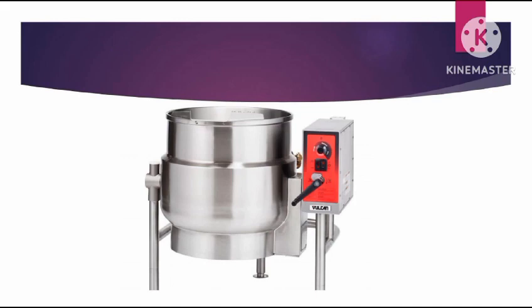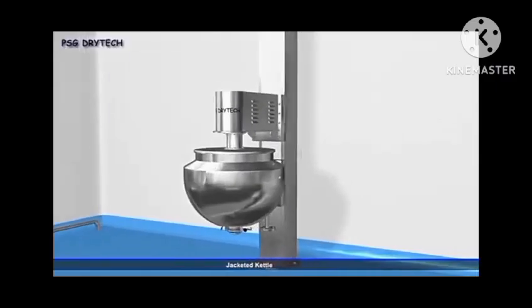Now the kettle may be fixed or made to tilt. A kettle of capacity up to about 90 liters can be made to tilt, but above this capacity the weight of the pan along with its contents becomes too great to tilt. Hence the bottom outlet is used to collect the concentrated product.